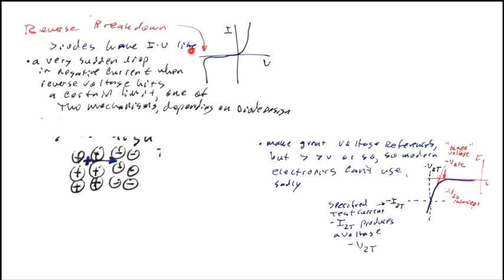You'd have many, many amps, hundreds, tens of thousands, millions of amps trying to run through this diode. And well before you even hit an amp, you would melt a bond wire, usually a solder ball, a bond wire, something like that would usually melt, and then poof, your diode's dead. But the avalanche process itself is not destructive.